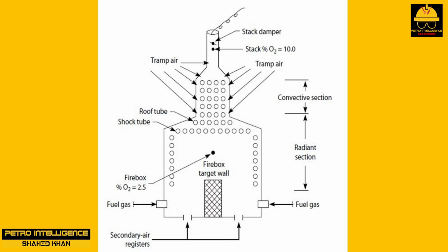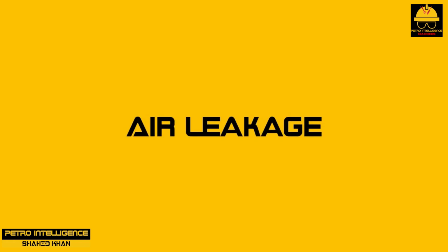Conversely, as we open the stack damper, the pressure at the convective section inlet will decrease, so that we have more draft. If we have too much draft, we will increase the risk of afterburn as we are increasing the rate of air in leakage in the convective section and stack. We adjust the draft with the stack damper and maintain the combustion air level by adjusting the air registers to accommodate the adjustments made on the stack damper.